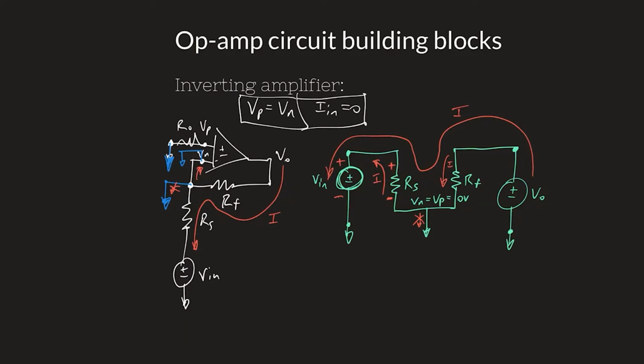But notice this current. If I have a resistor that I'm trying to use Ohm's law across, and I make some assumption about the polarity of the voltage across it, then if I go in and label the current through it, you always cross the tail and put a minus on the head.